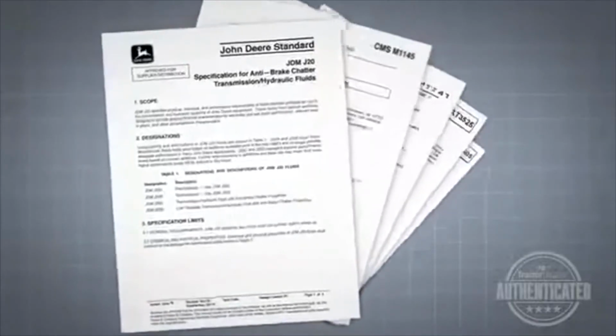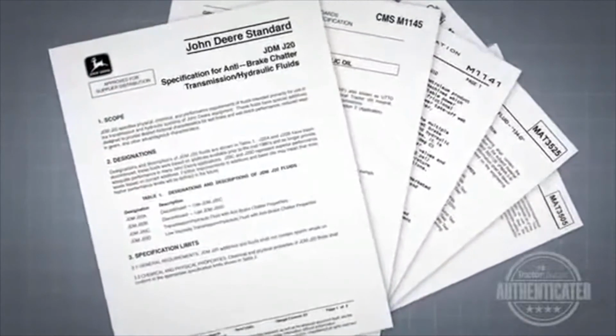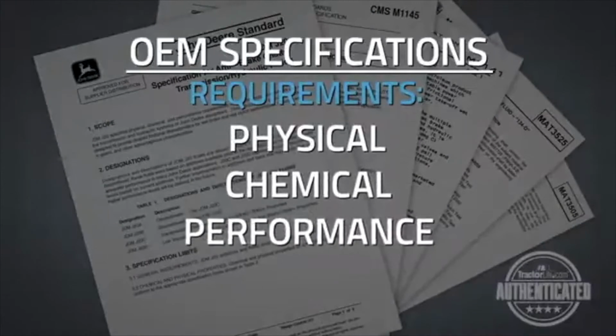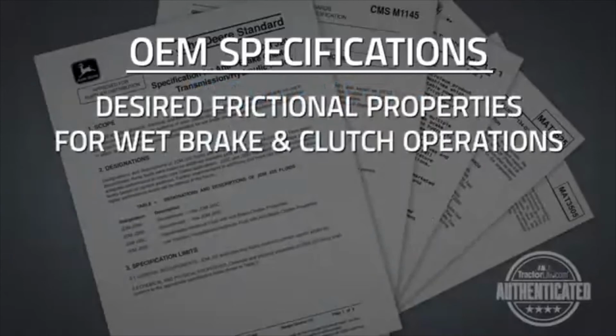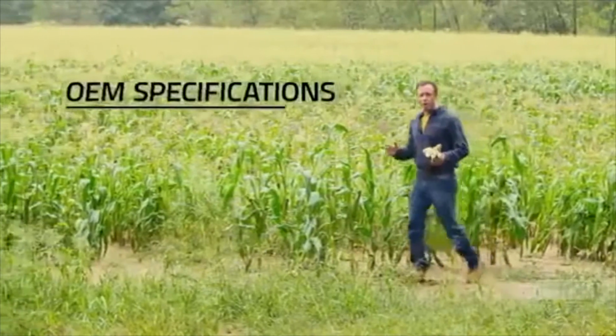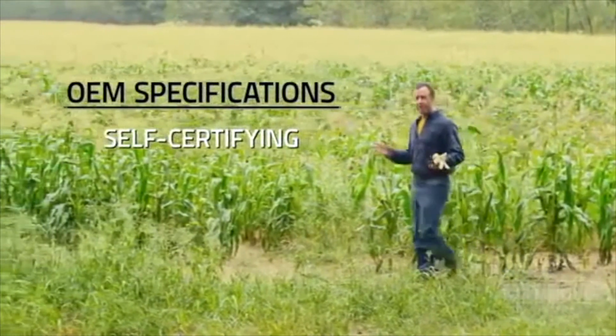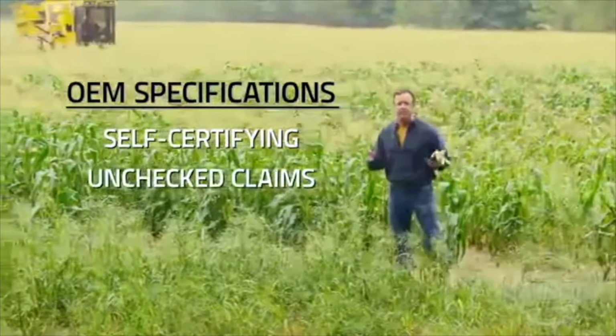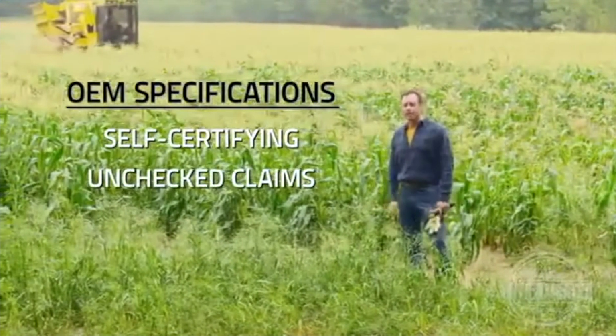So let's take a closer look at OEM credentials. OEMs specify physical, chemical, and performance requirements of fluids for use in their equipment. These fluids are designed to provide desired frictional properties for wet brake and clutch operations, reduced gear wear, and other performance characteristics. However, most OEM specifications are self-certifying, which means OEMs don't provide any real checks on claims that oil companies make on their product labels.